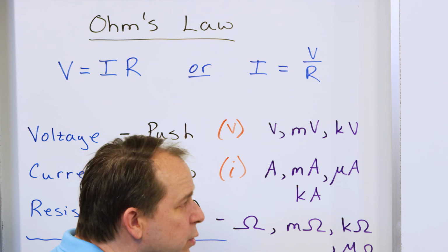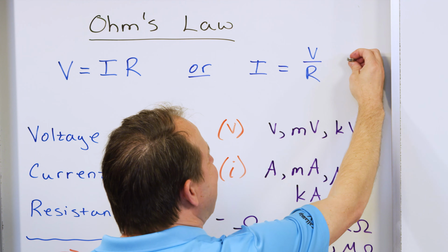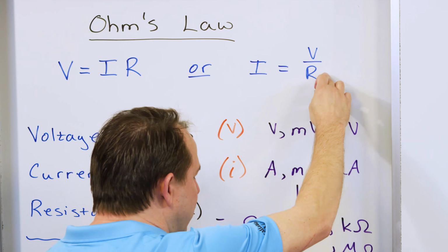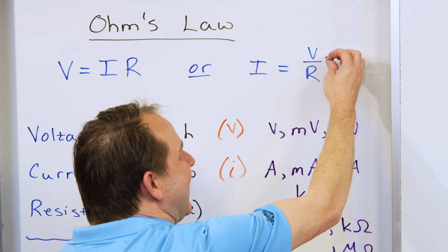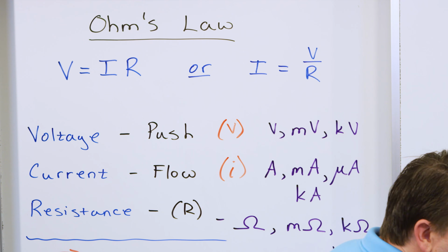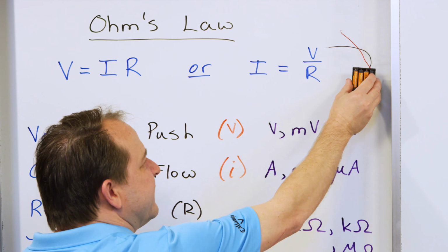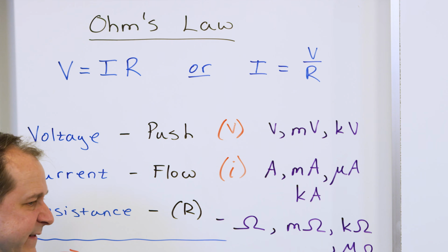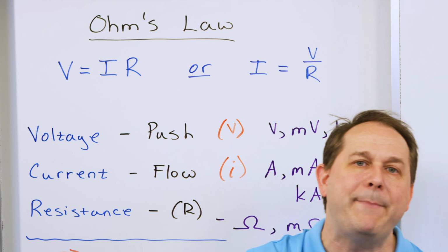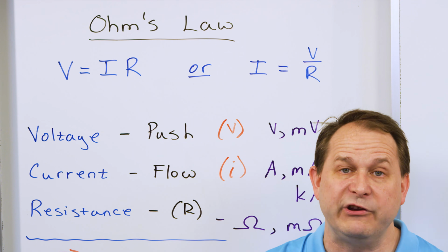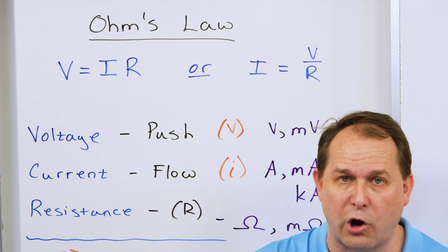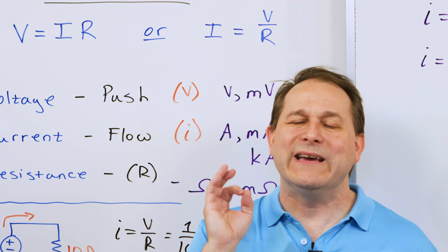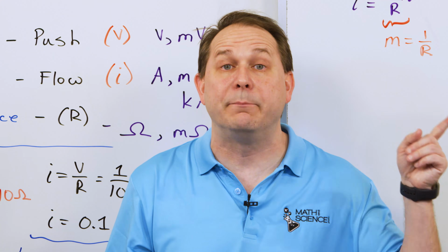But we also know that these 2 little batteries, when you add them together, is also 6 volts. So 6 divided by, if we do a 10 ohm resistor, we should get, again, 0.6 amps supplied by this. We can pick any of these others that we have used. This is about 6 volts. 6 divided by, again, 10 ohms, we should get the same thing, 0.6 amps. No matter what batteries we use, because the voltage is 6 volts, I've arranged them so they're all 6 volts. If I hook them up across this 10 ohm resistor, we expect to get exactly what we already got before.